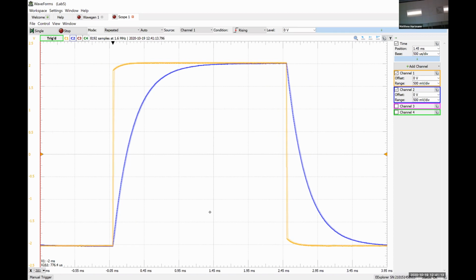If you look on your lab sheet, it says the voltage across the capacitor, which is oscilloscope channel 2, the blue curve, should have an exponential form fitting A e to the negative t over tau plus B. I'm going to ask you a simple question. Does that equation look generally familiar? Good. So what does B represent in this equation? Y at infinity, exactly right. It's simply the value that the voltage settles to after it's stopped exponentially increasing.